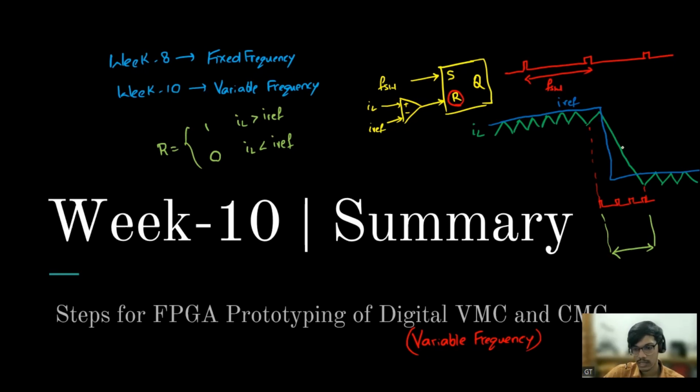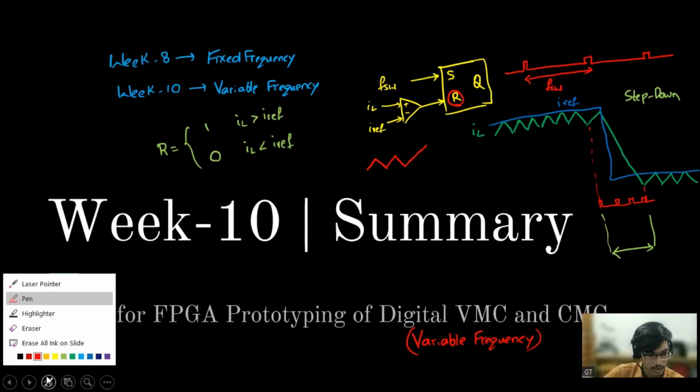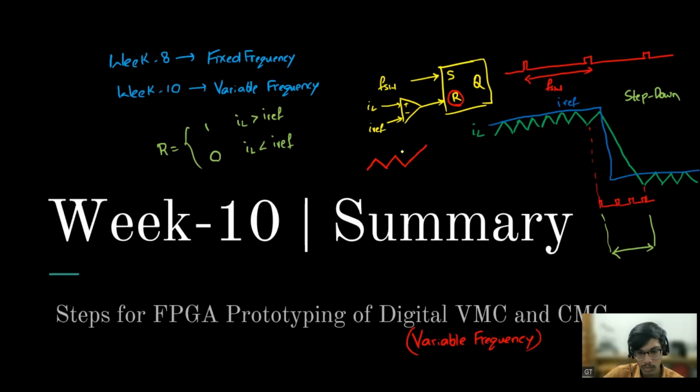In this scenario, where it is a step down transient, our I reference has gone down because the current has gone down, and our controller says I reference is less. During this region, it should completely turn off, right? Because it has to go down. And that's why it is reset dominated. Had it been set dominated, what will happen? At every set, say the inductor current is like this and it got reset. And if it is set, it will go in the other direction and the reference is at the bottom.